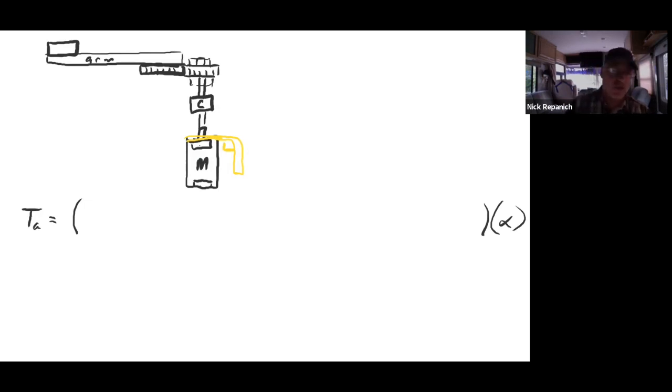Okay, so there are a couple of little rules that I've developed to help you figure out these inertias and how they appear back at the motor, because gearing changes things and inefficiencies change things. And in a minute, when I say things, I mean the torque. We could start this formula with I equals, but I actually found it easier to put I into there and actually calculate torque and do 2 things at once.